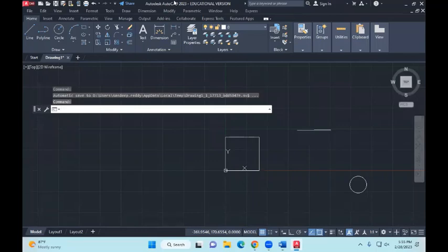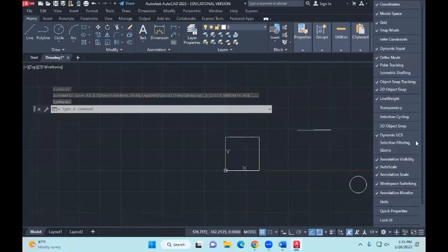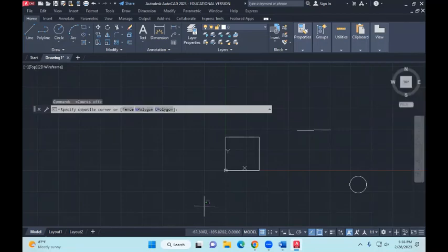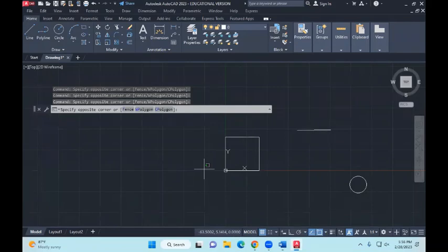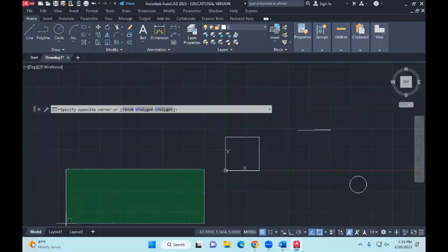Okay, so I'm going to repeat this again. The bottom right hand corner, if you need more buttons to play around with. Because this is the first time you have opened AutoCAD with your account, the coordinates would be off. So if you would like to turn it on, you can click on it. Now the button for coordinates will show down there. If you move your crosshair anywhere, it's going to keep changing the coordinates. Okay. And pretty much that is what I was going to talk to you about, the buttons.